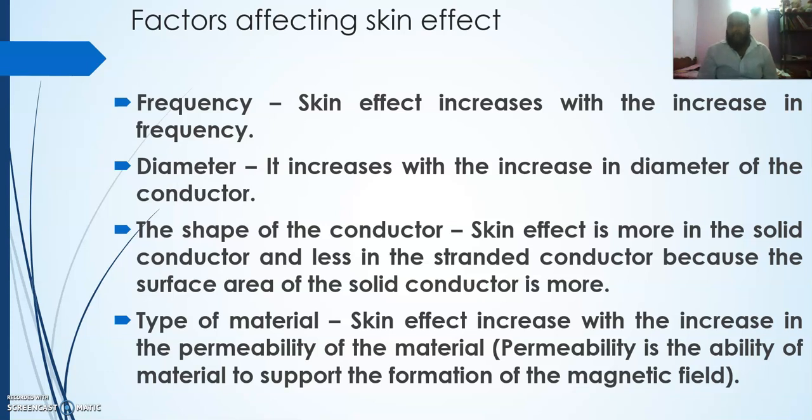About frequency, we have already discussed that skin effect increases with the increase in frequency. Next, diameter: it is directly proportional, it increases with the increase in diameter of the conductor. Next, the shape of the conductor: skin effect is more in the solid conductor and less in the stranded conductor, because the surface area of the solid conductor will be more compared to stranded.